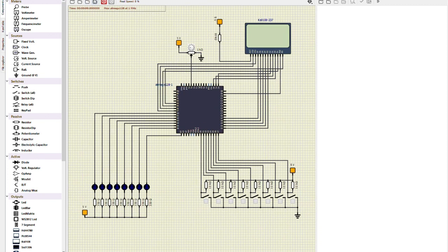So let's load the firmware. We enter the application, debug, and the hex. We use it, and as soon as it's loaded, we launch it. So what do we see here? It's just our application. Here are the D0 port, D1 port, and D2 port. D0 port is responsible for the door open or closed state, D1 is for ignition, and D2 is set for our lights.